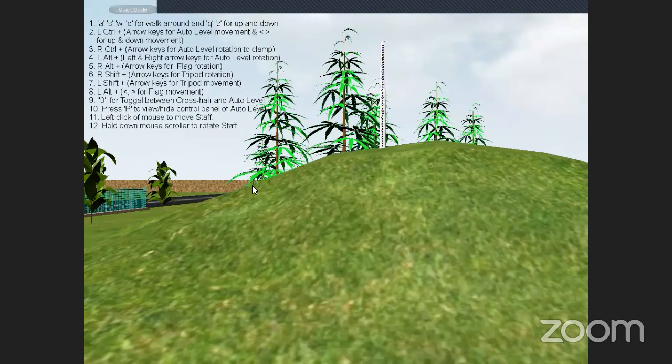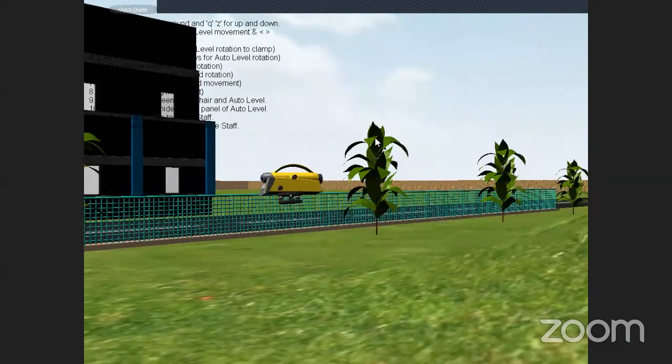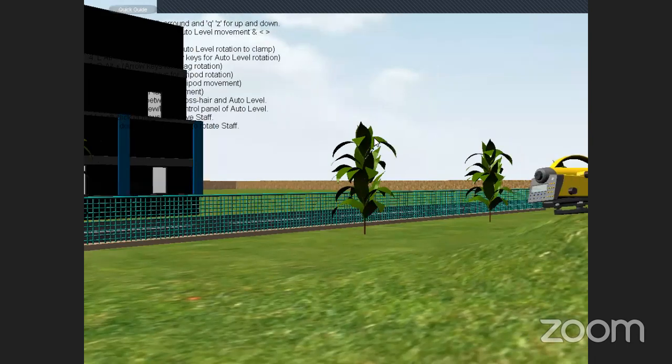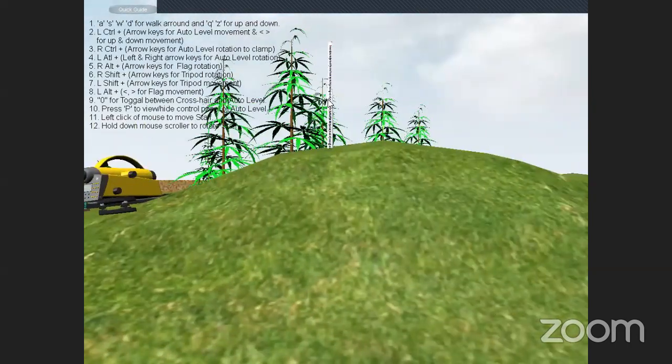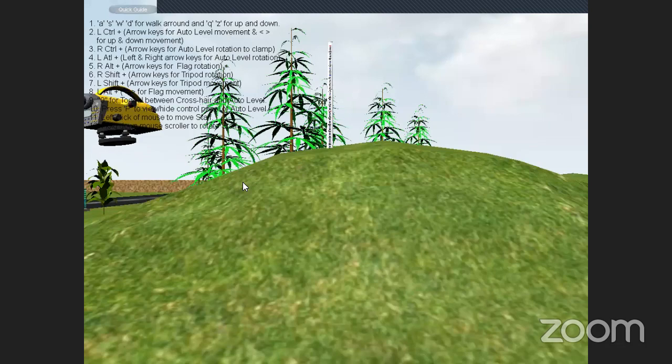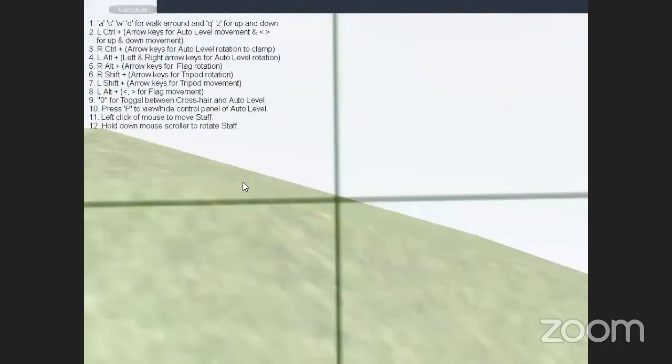Tripod also we need to move. Now for the time being, I am not moving the tripod. I am moving only the telescope to a convenient position between C and D, so that I can see. But tripod height, in an actual site, the tripod will have a fixed height. You cannot move like that in the actual field. But here we have an opportunity to move in a different manner, because we are moving in a horizontal plane only.